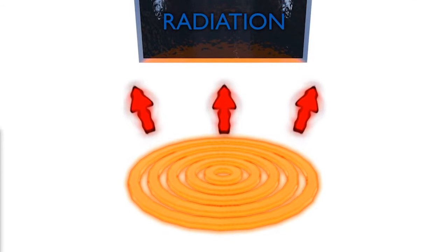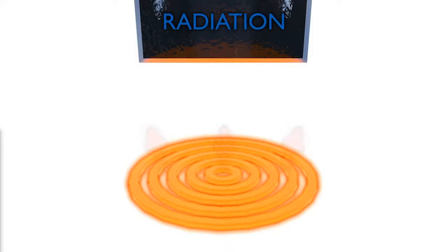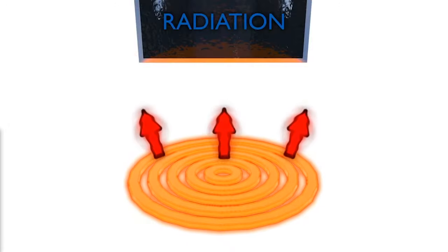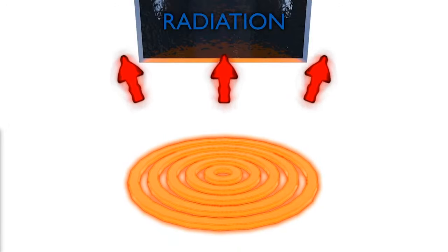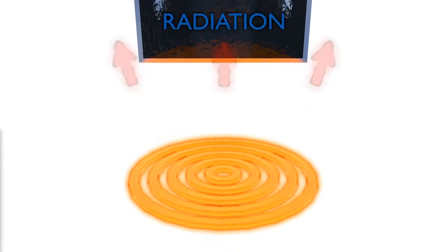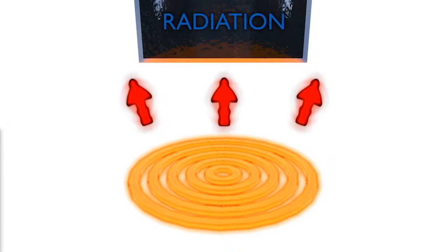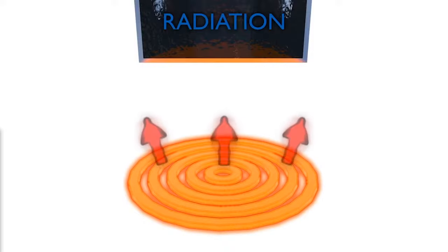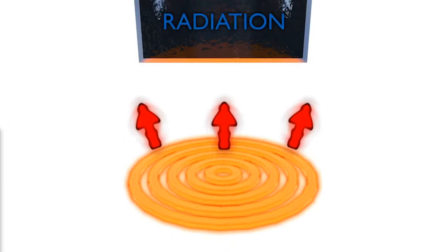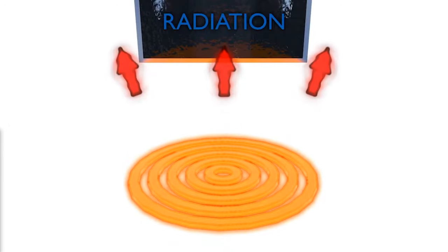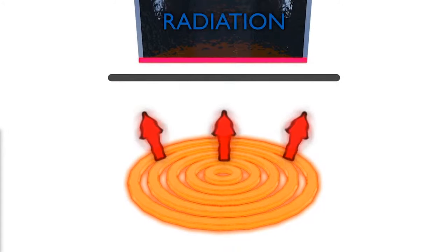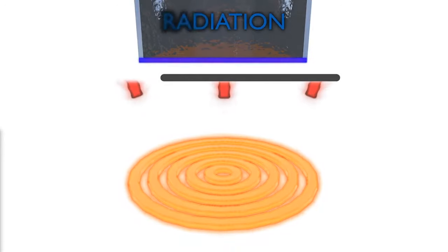Radiation is the transfer of heat from one material to another, which occurs by means of electromagnetic waves. Radiation does not require either physical contact of the materials or a fluid medium. A warm surface such as our hot plate will emit infrared radiation, which can travel across a space even in a vacuum. When these infrared waves strike another object, they are converted back into heat. The efficiency of this conversion process is governed by a property called surface emissivity. The lower this value, the less able a material is to absorb or emit heat via radiation. In construction, reflective foil membranes and foil-faced insulation materials can help limit heat transfer by radiation.